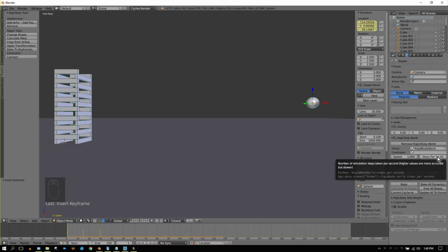It's best if you turn it up, in my opinion, to about 600, depending on how fast you have the sphere going and how fast you have this speed set. But typically, 600 is where it's ideal, in my opinion, as far as the trade-off between accuracy and speed of simulation, or the time it takes to do the simulation. But usually 300 is a pretty good number, and a fairly round number as far as making it work.